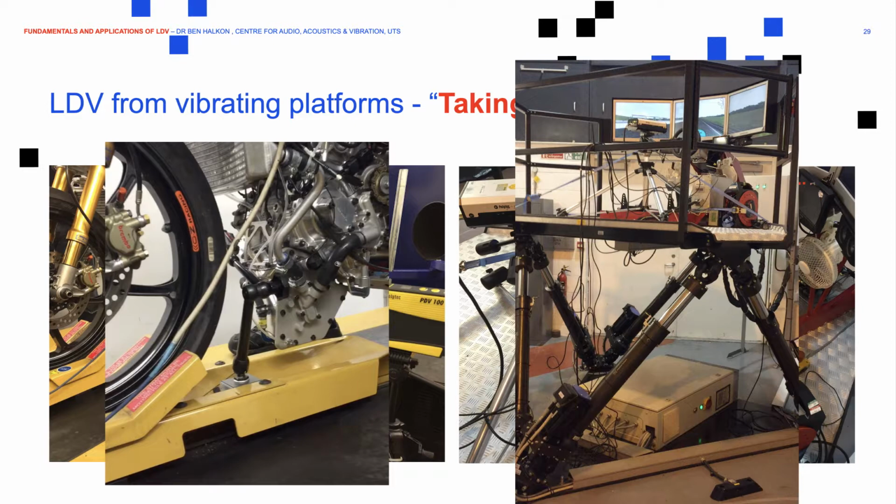This began life because we knew that vibrometers made a relative vibration measurement. So if this thing limps around, then we're sensitive to that. If we use a beam steering mirror, as is the case up in here, to direct the laser beam up from a horizontal orientation onto a difficult point to access within this single cylinder racing engine, then we're sensitive to that.